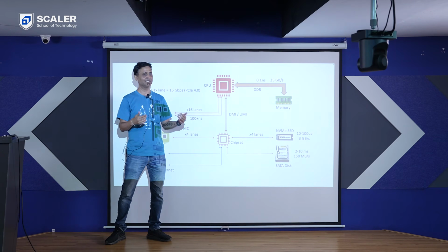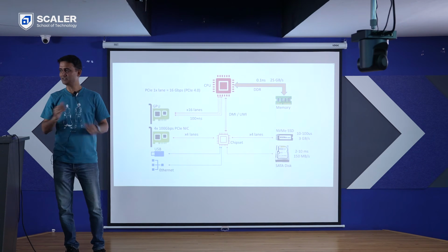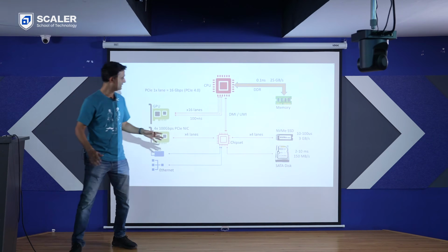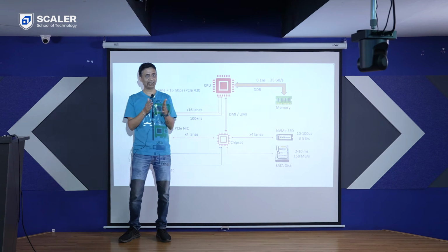For what it's worth, every single time I do this, for Intel's I remember, AMD's I always have to look up what the bus is called. Okay, principle is the same. All right, how many lanes? How many DMI lanes? 8, maximum 8. Now DMI electrically is identical to PCIe.